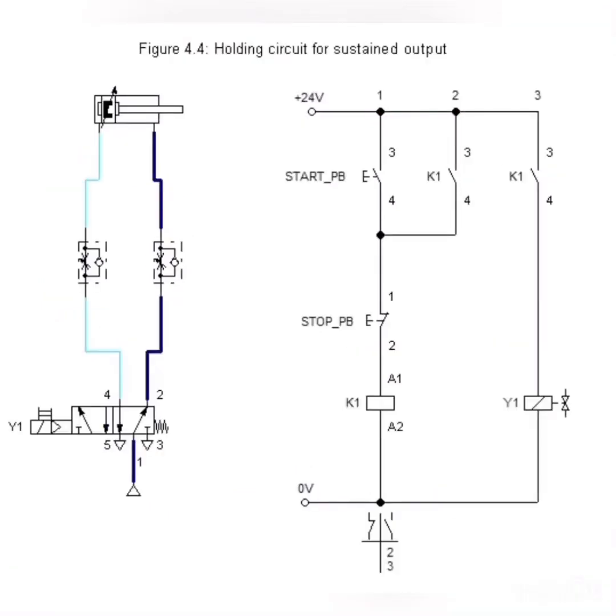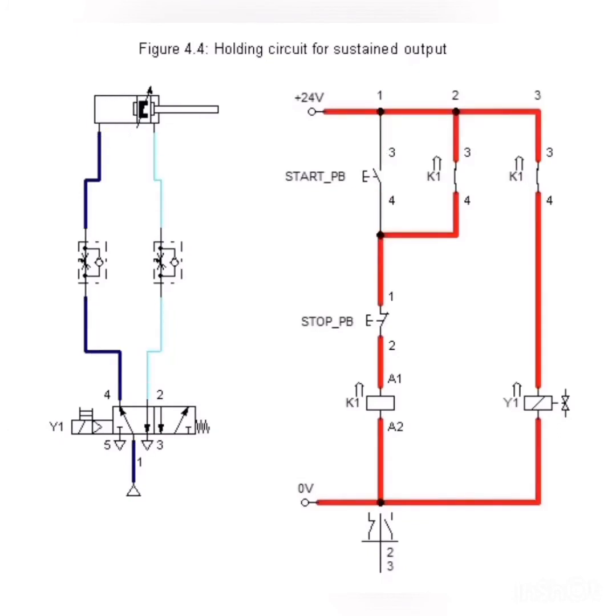When start PB is pressed, the actuator block will change from right to left and it will hence extend the cylinder and activate A+. Next, the circuit has a holding circuit where the electrical circuit shows the operation of the circuit. As the circuit has a holding circuit, the circuit will remain maintained at its last position when the start PB is pressed.